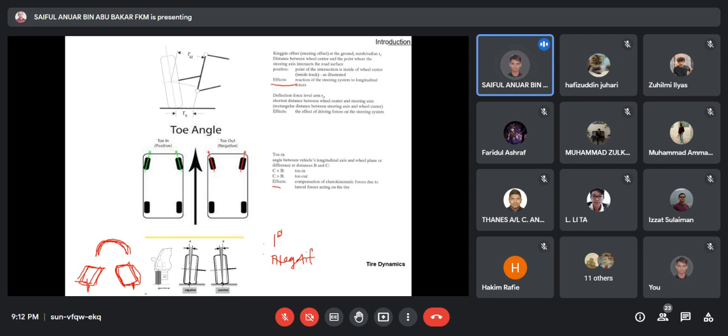The wheel needs to move up and down, so the upper part of the wheel hits the wheel arch. That is why on most modified cars with excessive negative camber, the arch is damaged, because the up and down movement of the wheel collides with the wheel arch.